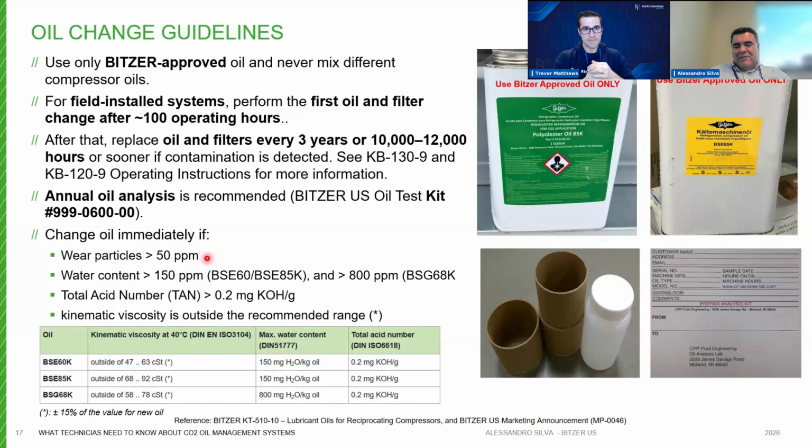If one of these parameters exceeds the limits we recommend, I remember once a customer contacted us to ask if we have any guidelines on how to filter the oil. I said, unfortunately, you have to change the oil. Especially for his installation, the oil was very dark, with multiple failures, especially motor burn.